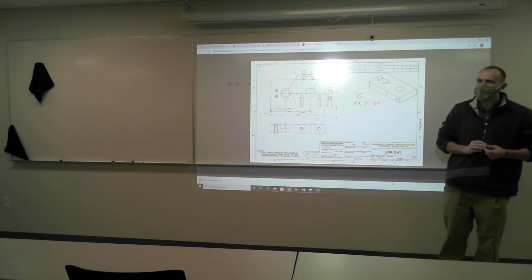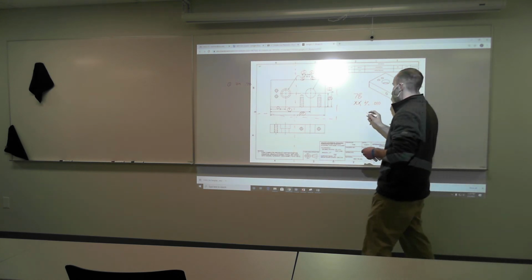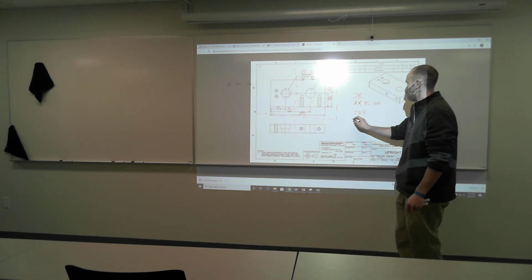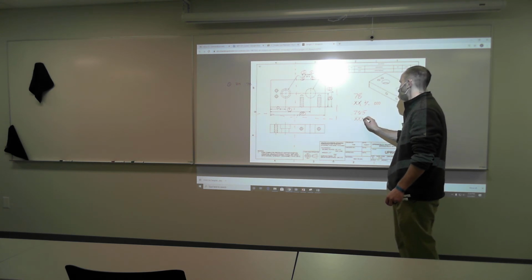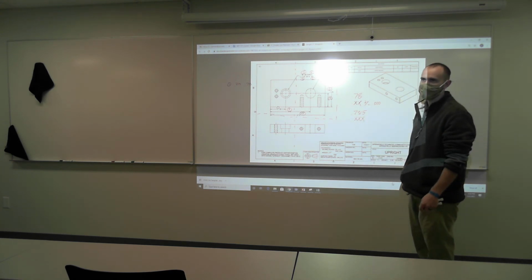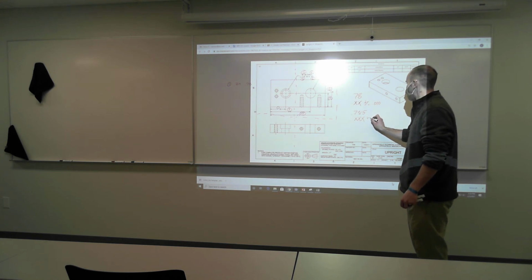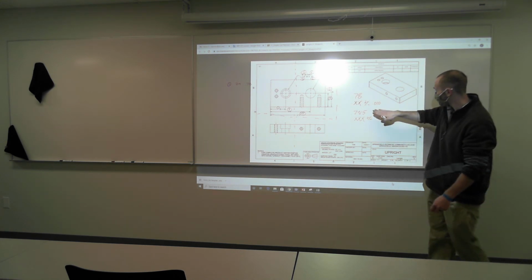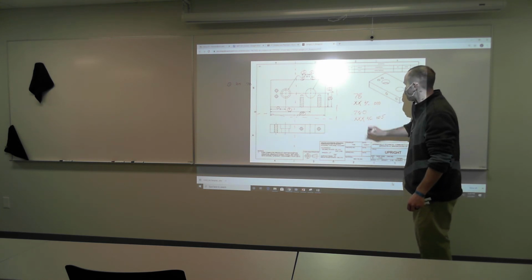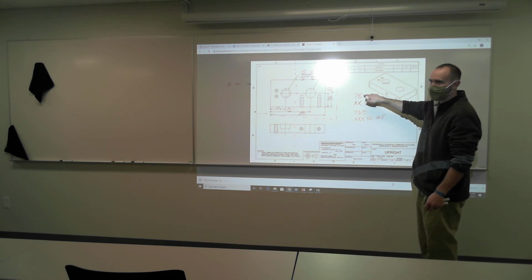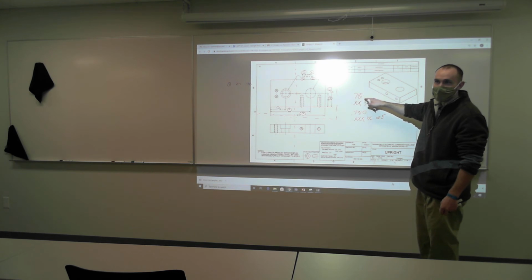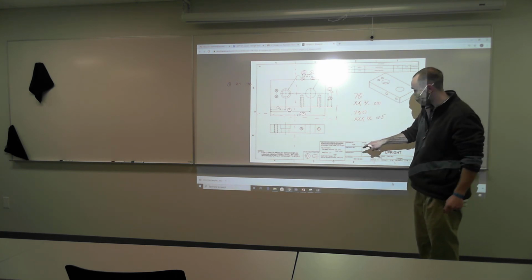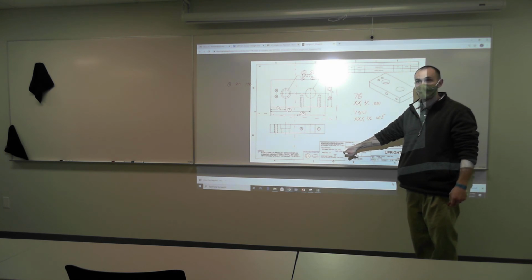Okay. Well, if we had a dimension that was 785 thousandths, first of all, that's a 3-place decimal. What is our tolerance if that's the case? 5 thousandths. Now you have plus or minus 5 thousandths. So very different implication here. Or even if that was 780, right? Technically, that equates to exactly the same thing mathematically, but this one implies more precision. It doesn't even really imply it. It straight up states it right here.